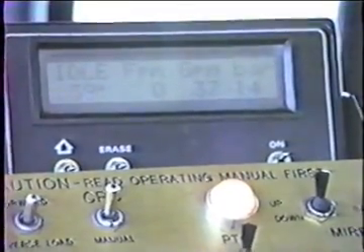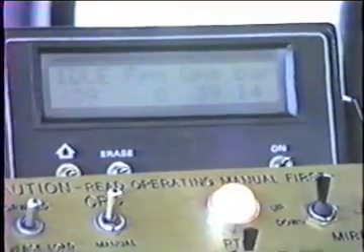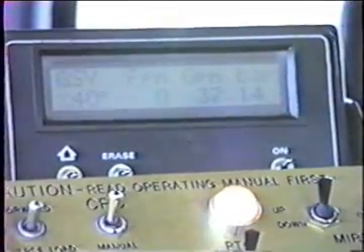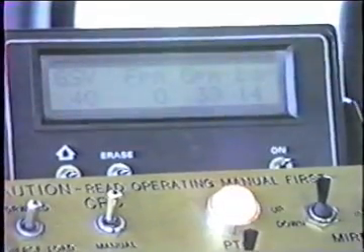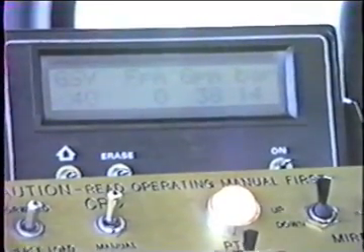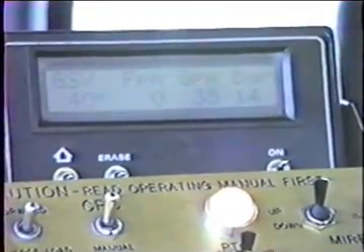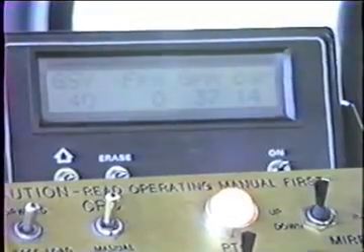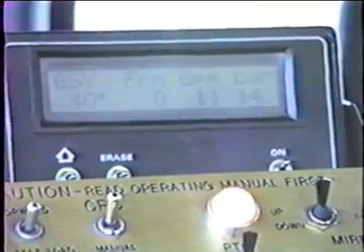Now if we go into the spread position from here, I'm going to move this up to where it reads GSY. That's what we want to see. Okay, and I turn it on to spread. Of course, we can't move because the camera can't keep up here. When we turn it to spread now, you'll see the GPM will actually go to 0 because it sees 0 ground speed. And there it sees 0, and that's just what it does, down to 0.